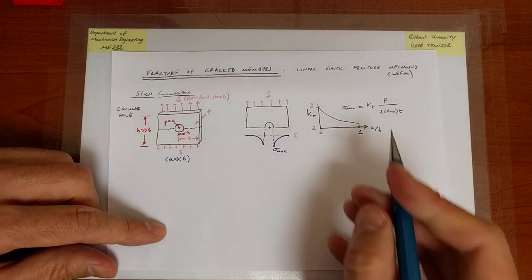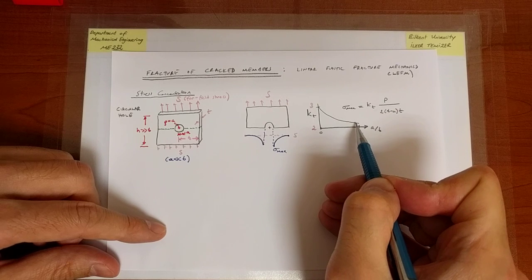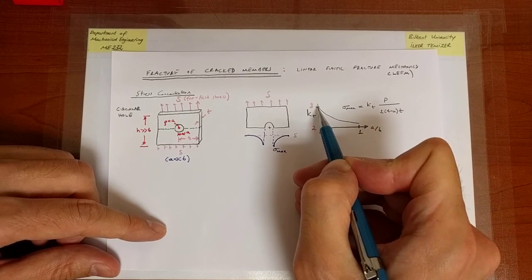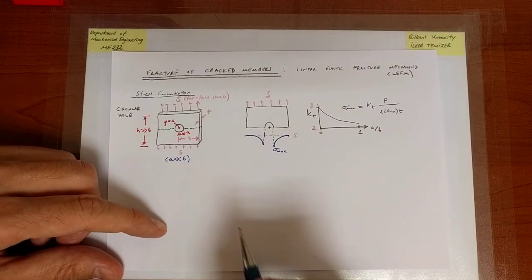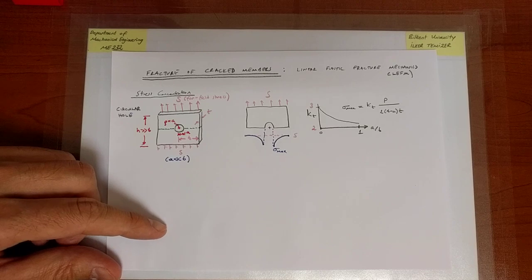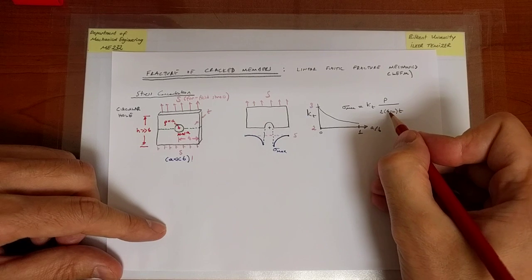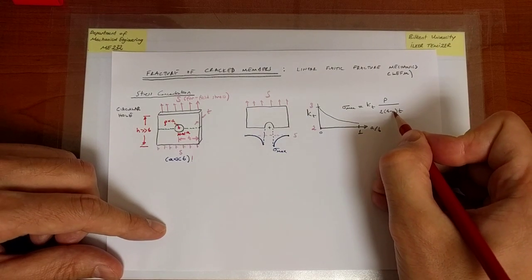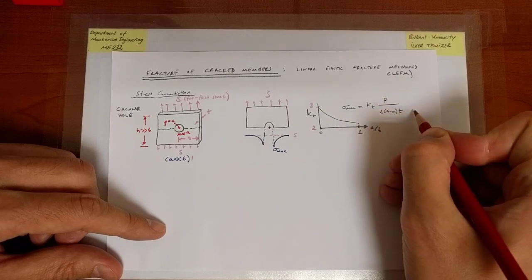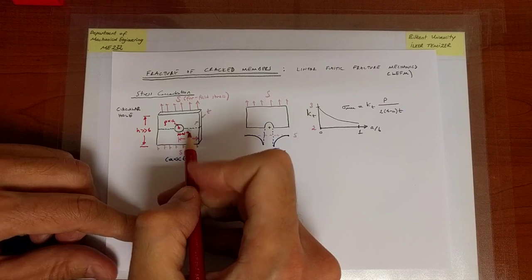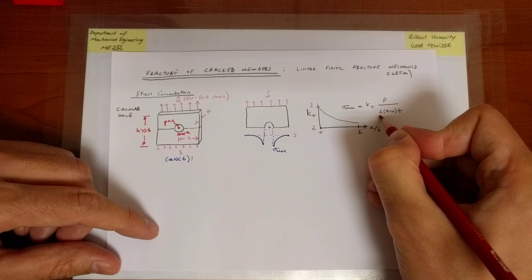Now the stress concentration factor, if a is large, then it's smaller. If a decreases, the stress concentration factor will keep increasing, but the largest value you observe is 3. What's important in this case is now to go back and invoke that assumption when a is much less than b. When a is much less than b, b minus a is approximately equal to b, and therefore P divided by 2bt, the load divided by the width times t, should be equal to the far field stress.